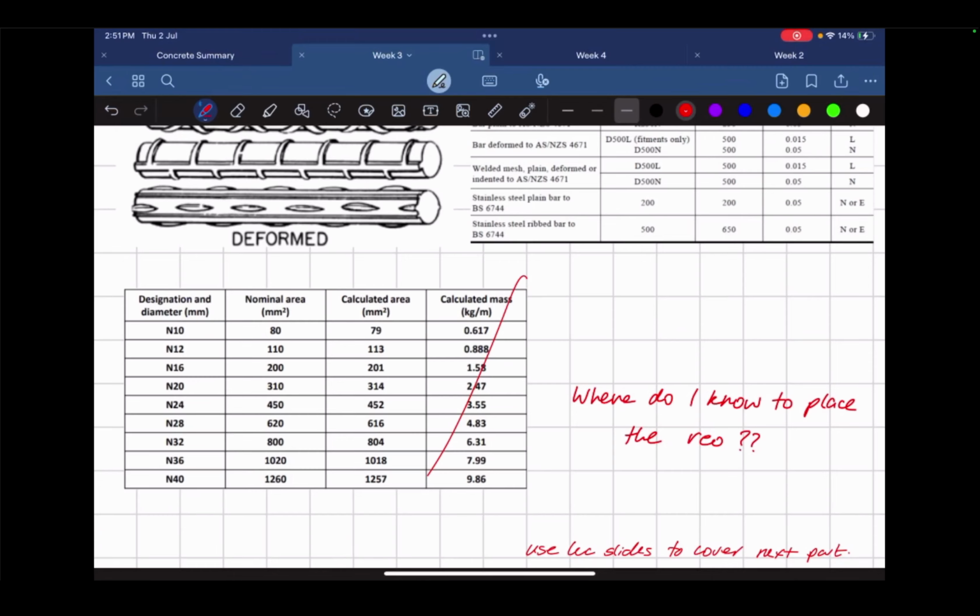So what is the bending moment diagram normally? Like that? Yes, so the bending moment diagram looks like this, with the positive up front. But this convention is incorrect. You guys will learn that in 2, 3, 3, the proper convention is you draw the positive at the bottom. The positive stands for tension.